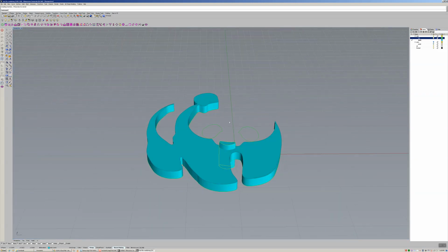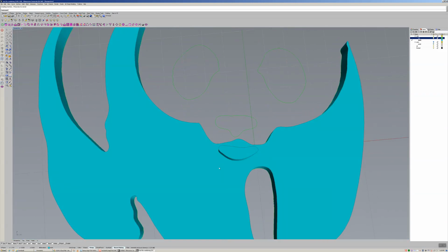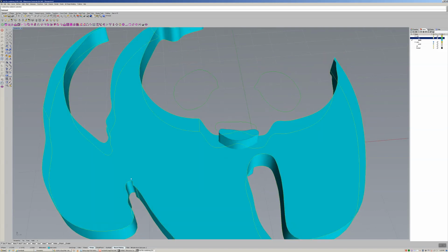And now here's a new command, it's a Boolean Difference. This is just a fancy term to say subtract. So I'm going to choose what I want to keep, which is this big object. And I'm going to go to these little balls over here, click and hold it down, and select Boolean Difference, which is the second option. Now it's asking me what I'm going to subtract from, which am I going to cut from. So I'm going to choose that object, right click, and it kept it. So I just delete it, and then there's the hole.